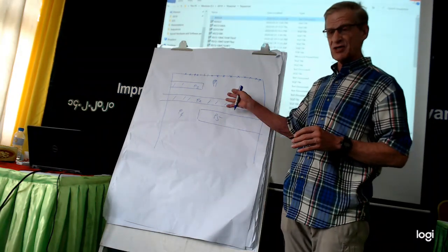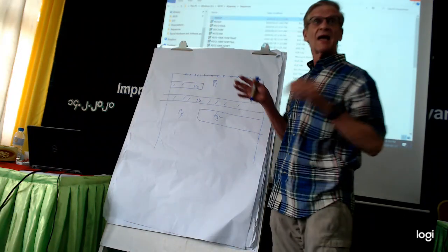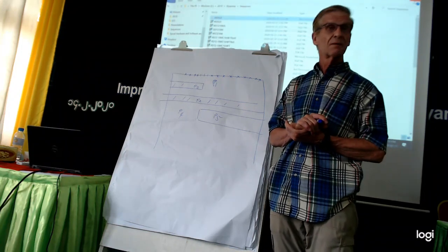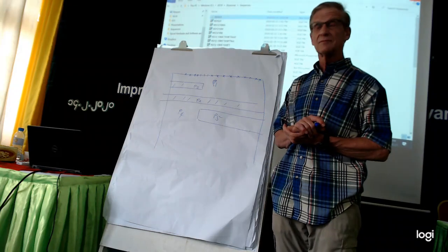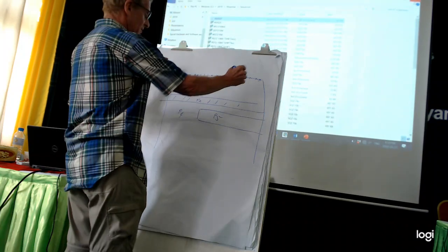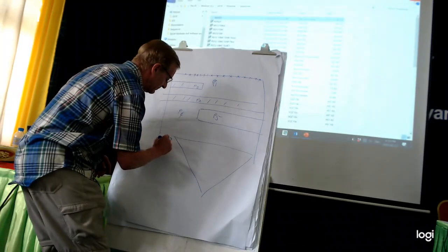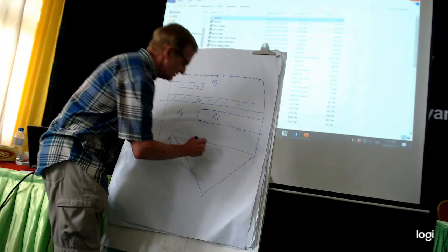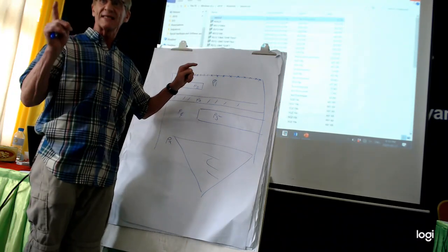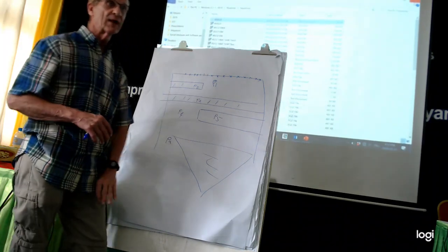So the proper way to attack this, to see if you have a chance of finding this, is actually to set out a proposed array and then do a numerical simulation of the data. So you simulate the data, and then you've got, you know, sort of an apparent resistivity, right? So you see something in here, and you do this twice. You do it without this aquifer here, and you do it with.